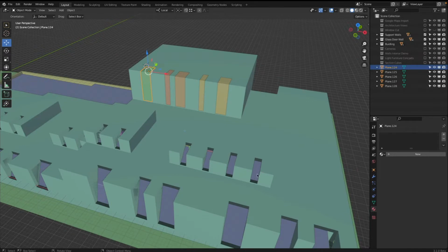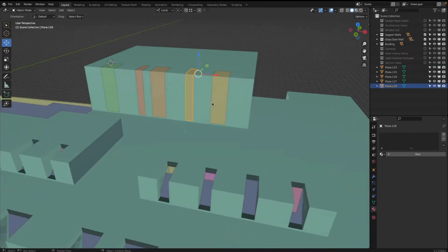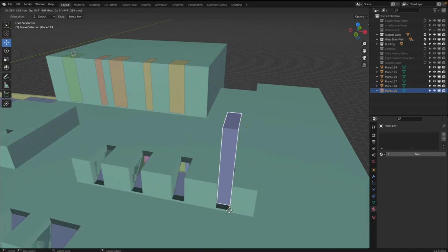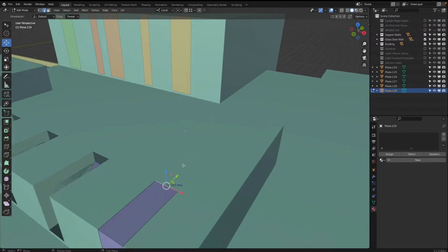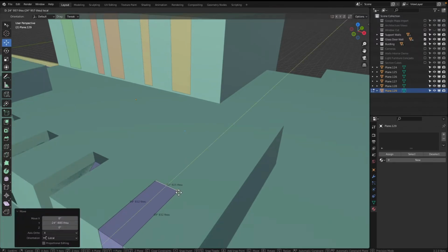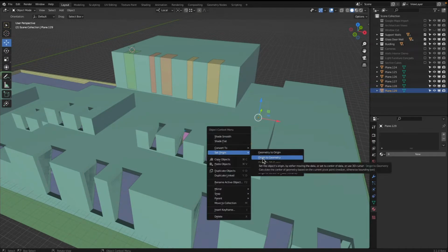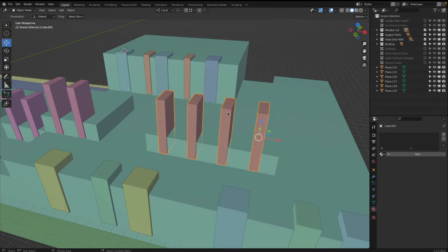And it's a little bit different than here, for example. So I will do this, Shift D, hold Control, okay, to this bottom part, go into edit mode, move this down, hold Control, snap, bring this over, hold Control, snap, okay, good. And then I will right click, set origin to geometry, because window cut there.